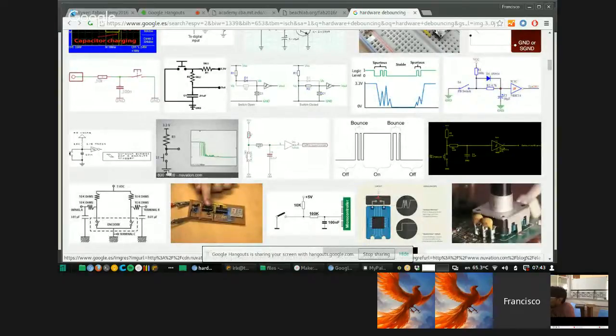to modify it, like hacking inside the board. I don't want you to mill a new board, but I want you to hack your board and add a capacitor and check again in the oscilloscope if it is happening like this. Okay. So about the bouncing, this is what I want you to do today about digital inputs.